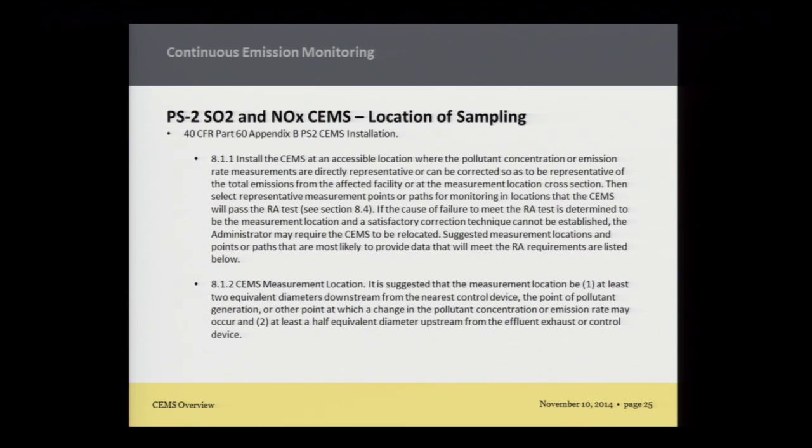Yeah, but if you install your CEMS, you can't traverse it. That's right. You've got to take all of that. Typically on a stack, you're going to see it up at the top, and that's where your stack testers are going to test. But an H2S and fuel gas may not have a port, it may be 100 feet that way that we do the RATA. But as long as the two agree, then you do your reference method 100 foot down and meet all the requirements. And if it matches your CEMS, then you're good, or your GC or whatever you're using for H2S and fuel gas.